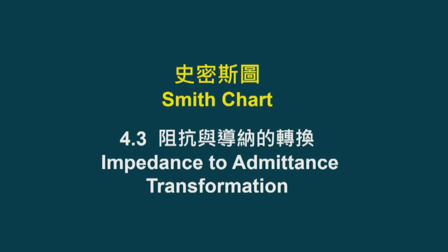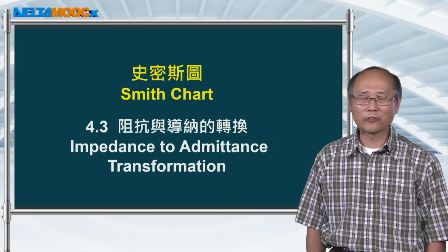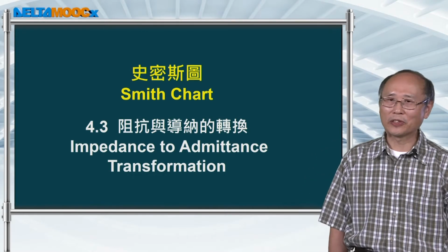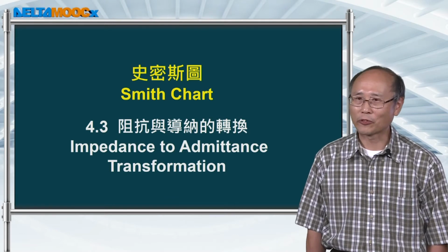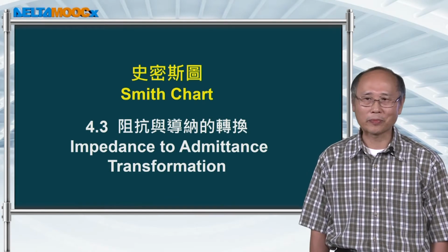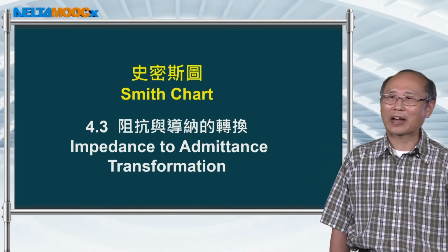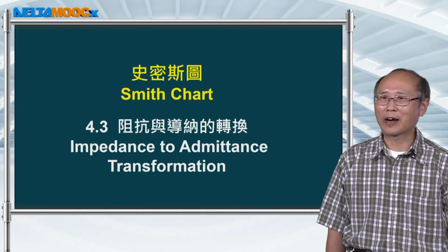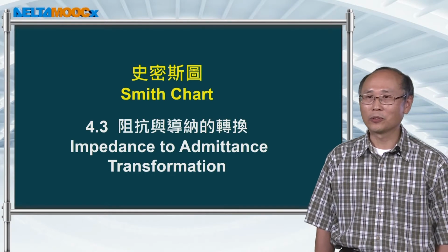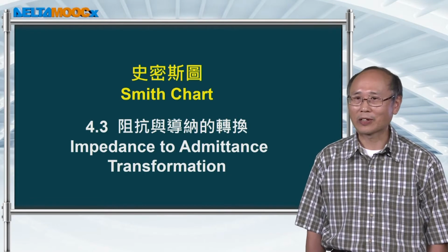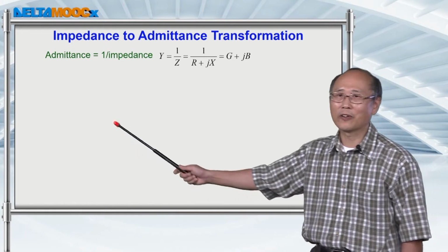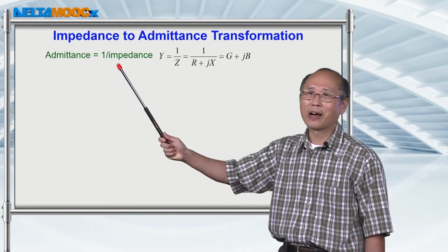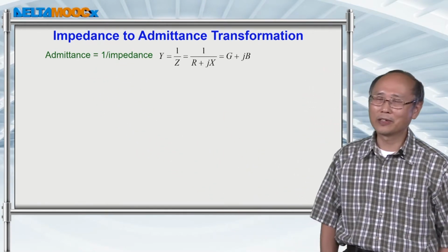We just talked about the Smith chart applied to searching for the input impedance and also the standing wave ratio, signal maxima, minima, and so on. But in fact, a Smith chart is quite powerful. It can also be used to look for the admittance of a circuit.